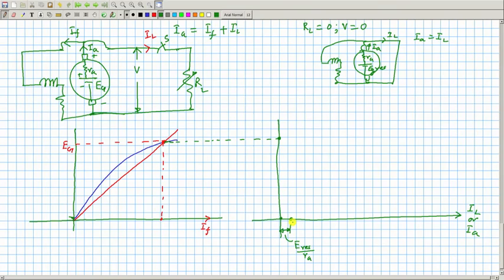Now, the question is, in between then what happens? It is like this. So, this is the no load voltage, this point, we say no load voltage or open circuit voltage. Suppose I increase the load gradually, I am drawing a little current from the armature. Then I know this voltage will be equal to Eg minus IRA.